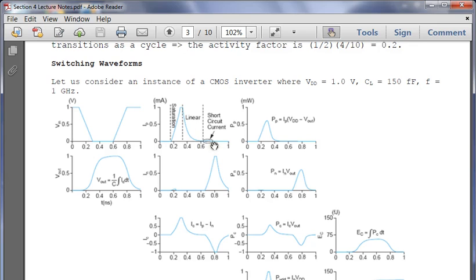At this point here, we're actually switching again. The transistor should be off. Any current that's dissipated when the transistor should be off is short circuit current. So it's the same thing: you have a very small amount of short circuit current here on the NMOS transistor, and for the other switch, it consumes a lot of current when it goes into saturation and goes back into linear mode.